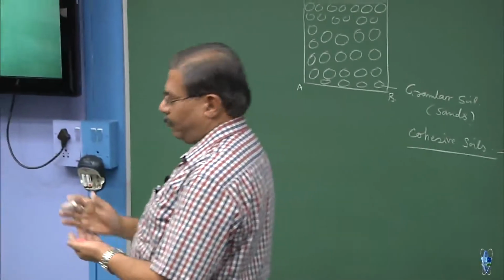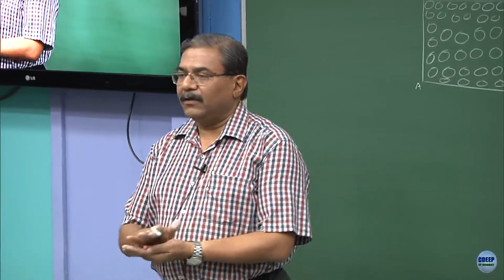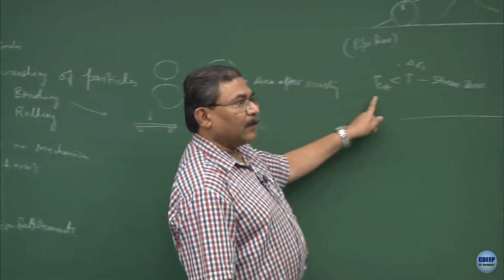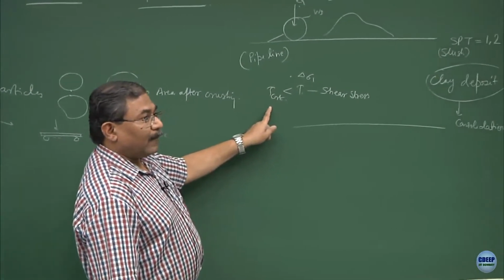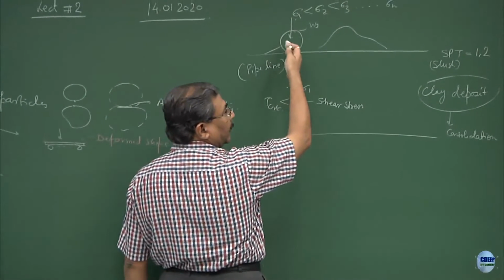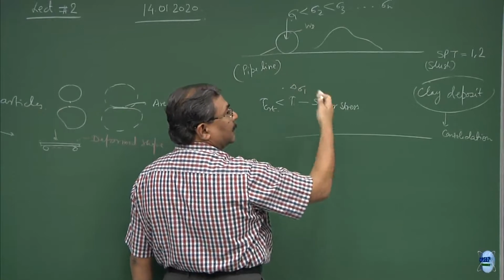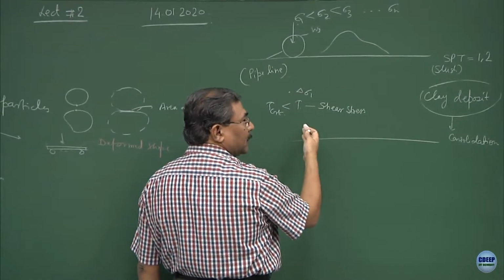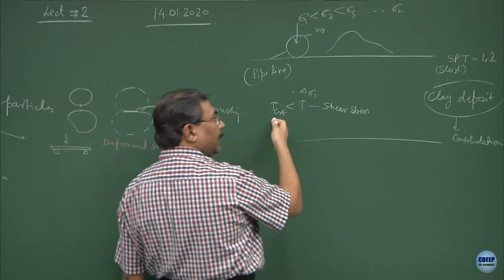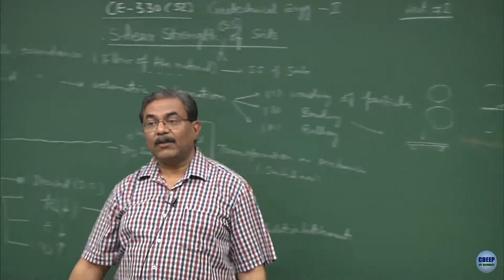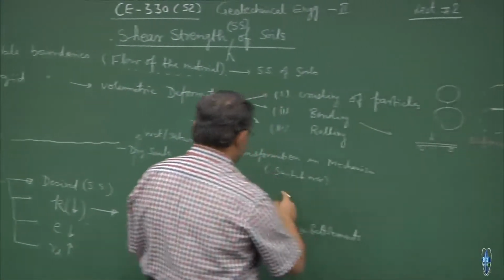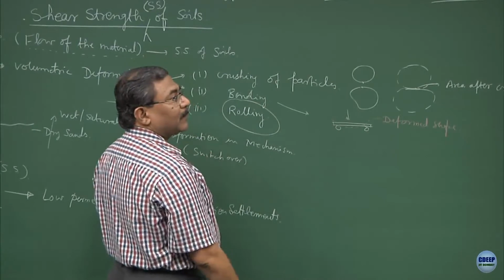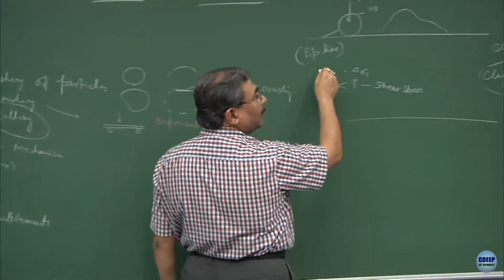Very specific case of the strength of materials which you have done in your undergraduate courses, alright. You know how to find out the critical shear strength of the material. Now, what I have created is a situation where, because of the external loading, settlement occurs, and beyond that critical load, the shear stresses develop in the system, and these shear stresses, if they become critical, much more than the critical shear strength, what is going to happen? So, here in the granular system, this was the rolling. In case of the cohesive material, what is going to happen? There will be a slippage.